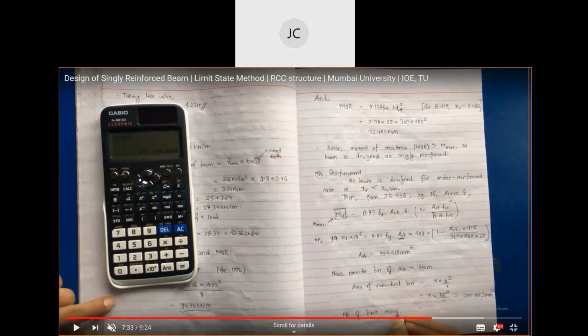Okay, so now for a singly reinforced beam, you can see everything is written here, page number 96. From this page you will get Mu equal to this equation, the moment of resistance for this kind of beam. In this equation, all the values are known except area of steel. Mu is known, this is 94.75 design moment. Fy is known, 415, because grade of steel is 415. D we have already calculated, and in this part also all the values are known: Fy, B, D, FCK.